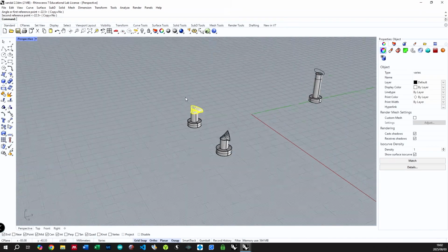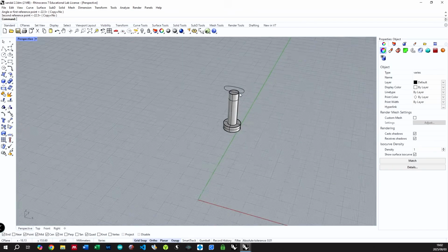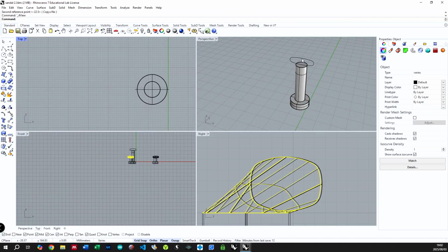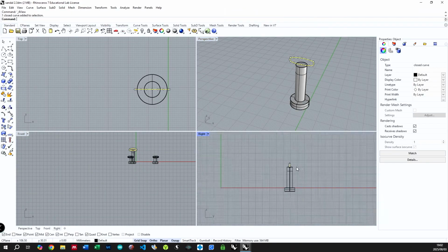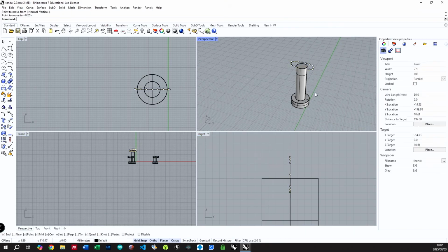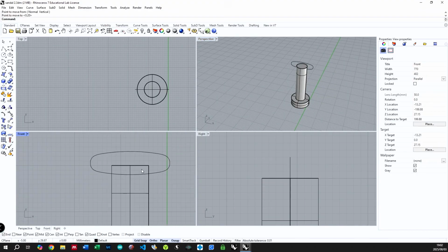Now my last or second to last step is what I want to do is I need to draw rails from here all the way through to there. But I just need to rotate that guy first and put that in the right position. If I grab that curve now, you will see it's a little bit too high. I need to drop it down 2 millimeters, so when I try and Boolean union that later, it will actually fit and have a smooth flat blend.